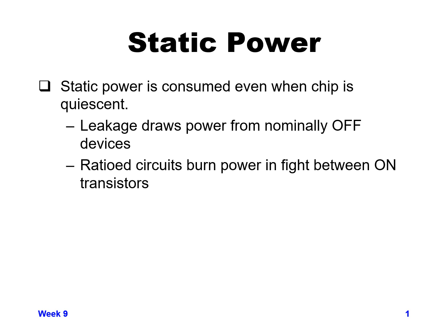And so in particular, if you have some sort of ratioed circuit or pseudo NMOS or something, when you know that it's not going to be doing anything for a while, you almost have to have some way of turning off that contention because it's a lot of power to consume.